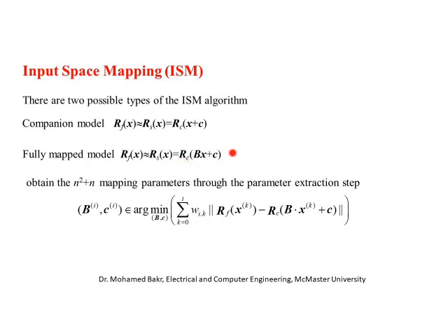Okay, you optimize that surrogate model, you're going to get a new design. You check that design in the fine model, see whether it's good enough or not. If it's not good enough, you are going to add the point that you have to the set, so this becomes i plus 1, and then repeat the parameter extraction again to get a better mapping. And you keep on repeating these steps until you obtain the desired mapping and the desired response you are looking for.